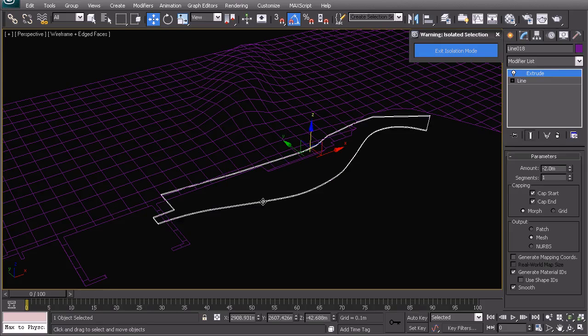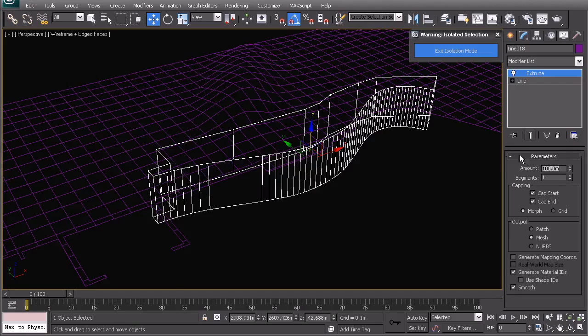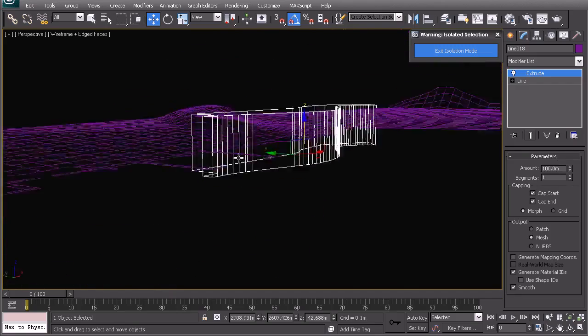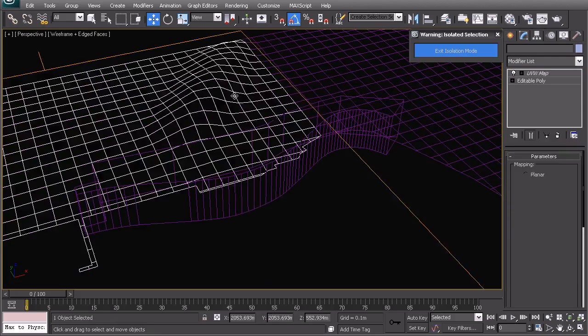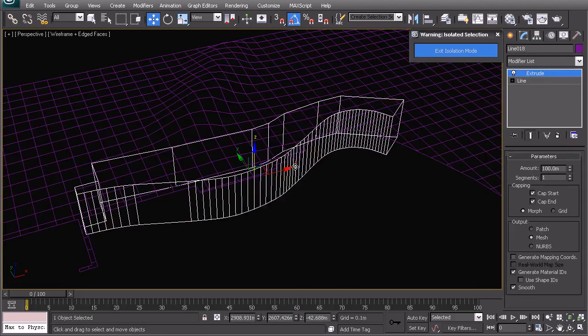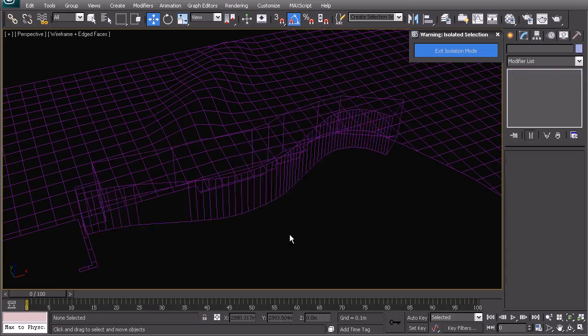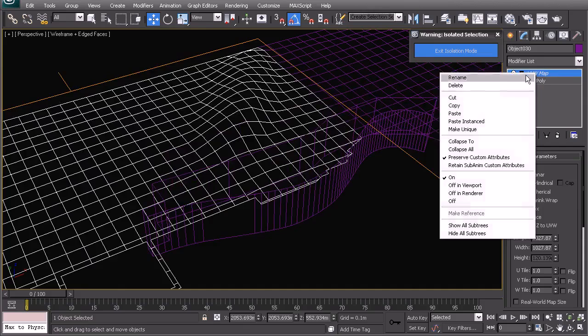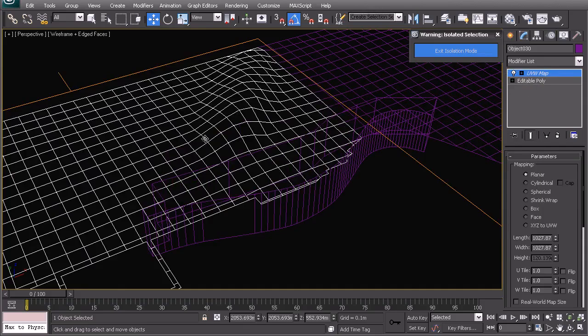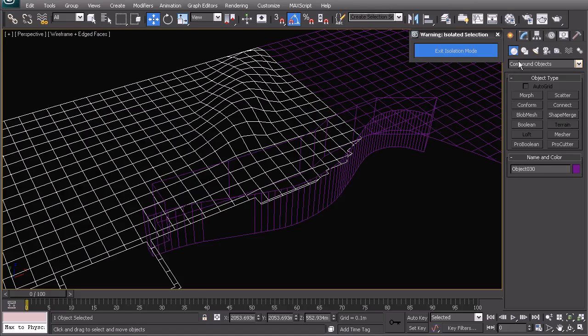And now we're going to extrude this slightly higher. Let's say 100 meters should be enough. Just double check that. We're going to need two of these objects since we're booleaning from this one and this one, so you can go and Control V, just make a copy for yourself. Now selecting this, you may just want to copy the UV map, which will be lost as we do the boolean process. So let's go to compound objects.